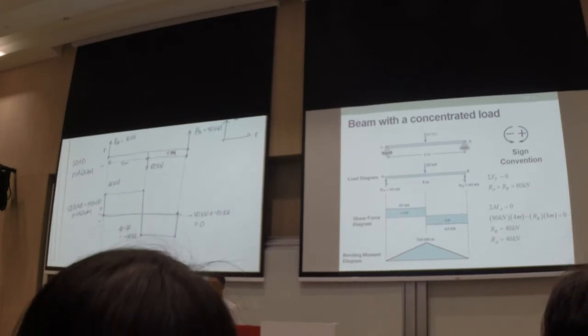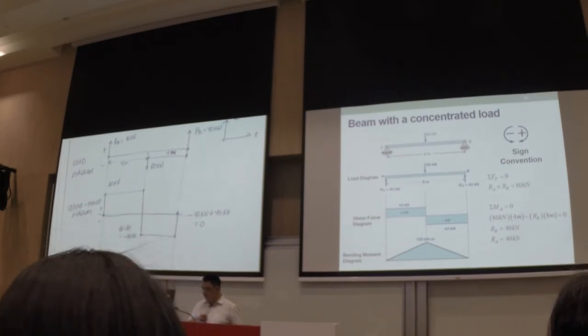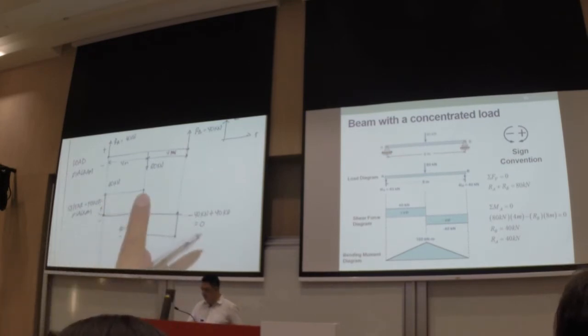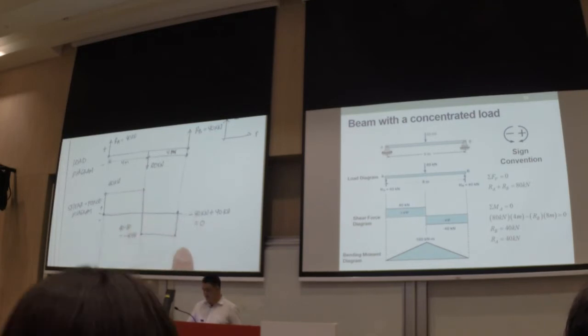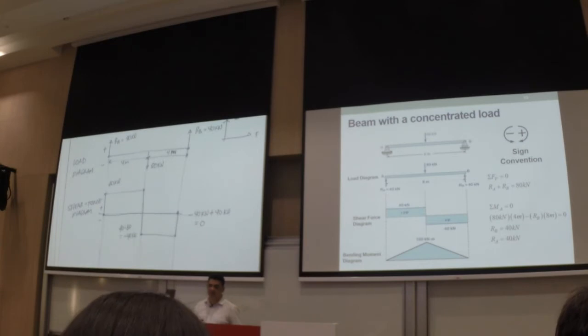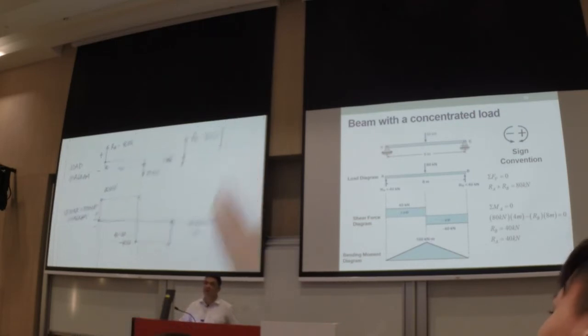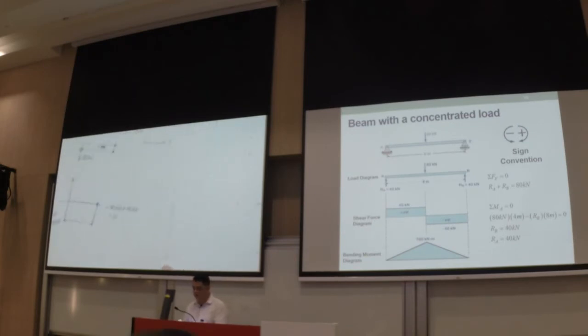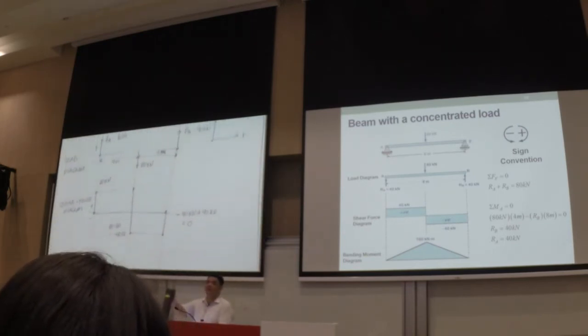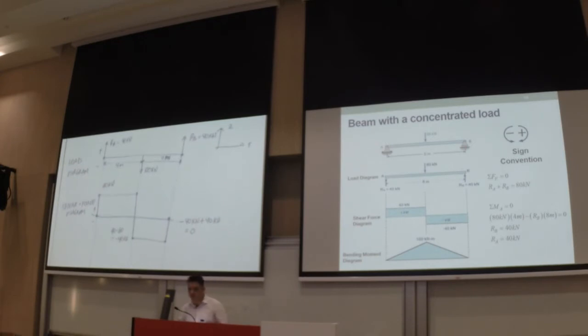Shear force diagram. So what's your maximum force here? Your maximum force will be 40 kilonewtons. Assuming it's negative 50, then your maximum shear force is that negative 50. Anyway, that sign just means it's along or opposite to the direction of axis 2. So that's the shear force diagram.